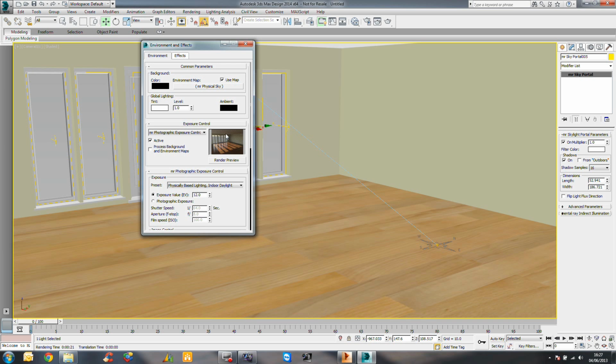It takes the light through the window and it essentially says light's coming in through the window, it's going to expand, it's going to hit the floor, it's going to hit the walls, and everything's going to react the way it should, and therefore it will light up the inside of the room, which is what you would expect in real life. So it's kind of given us a result that's not bad. So I'm not actually going to change these modifiers or these multipliers at all. If you were still getting a result that's too dark, you would simply up those multipliers on the right hand side a little bit.